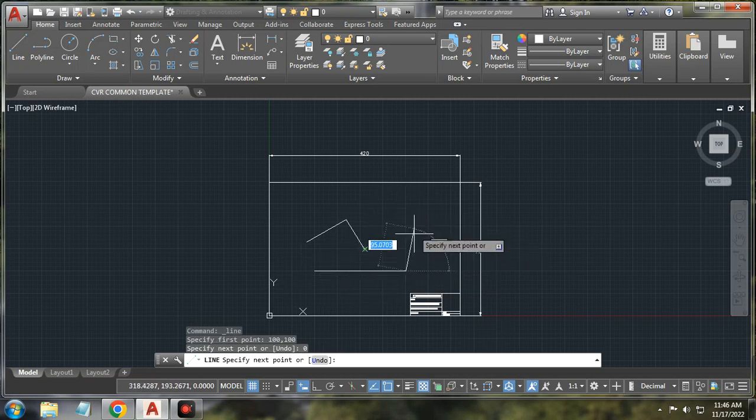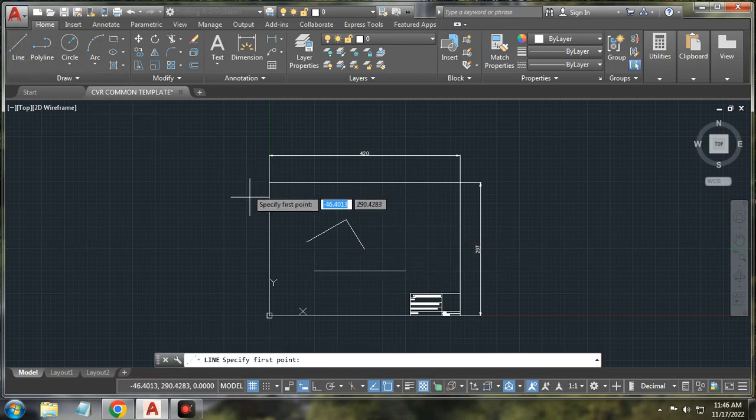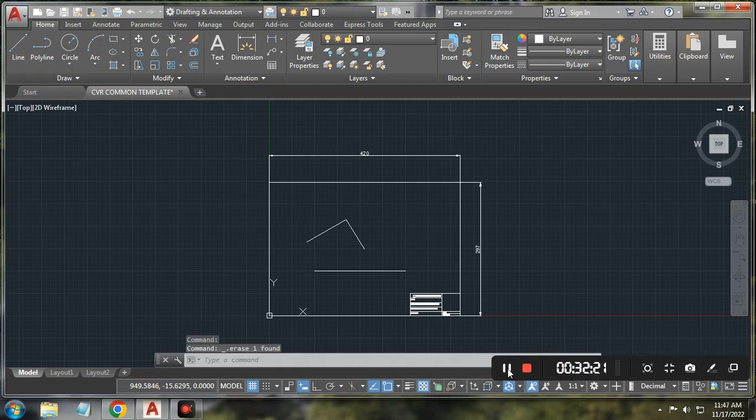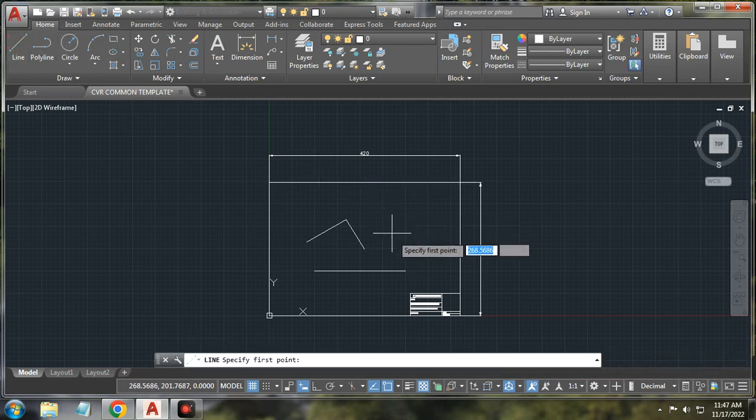Okay, y is fixed here, so that you get this kind of points. Similarly, if you want to give the two coordinates, directly you can click the point here. I will click the line, so directly I can give it as 150, tab, 150, click enter, and we'll add the second point.